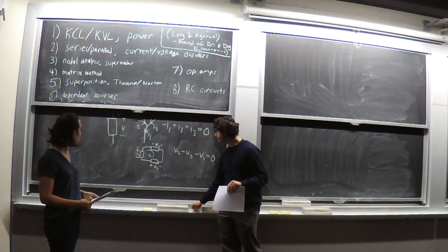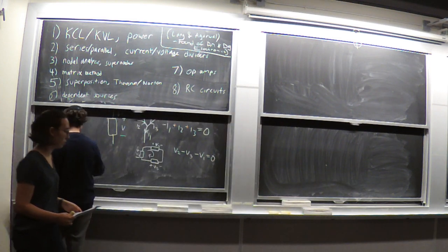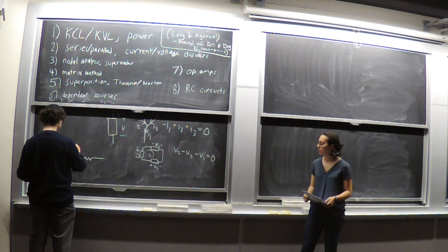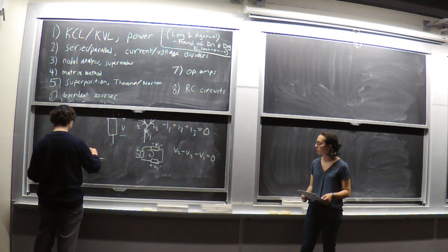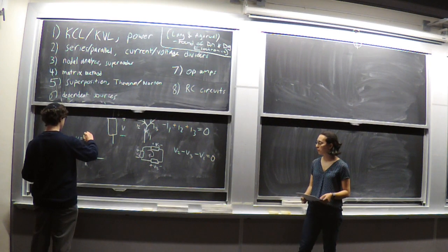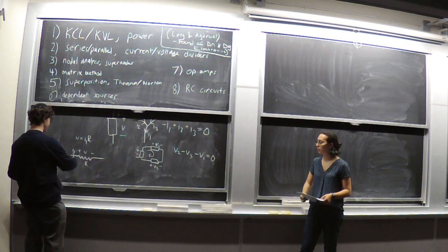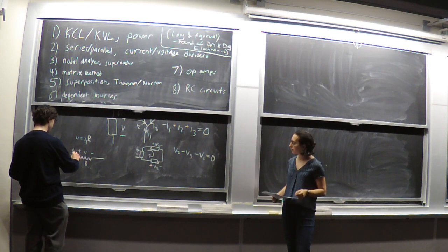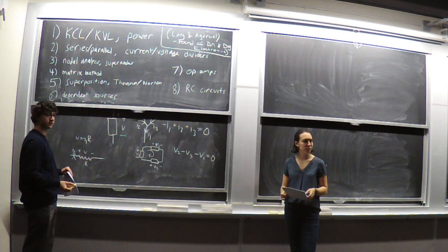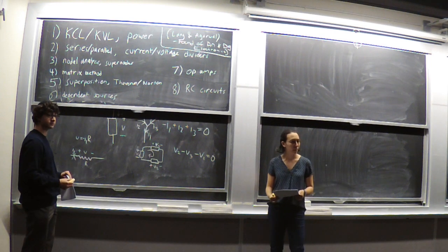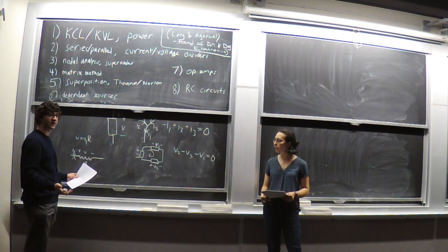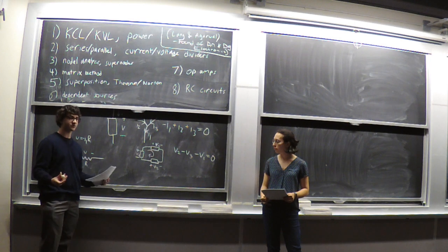And so, if we have a resistor, and we've defined some current going this way, and the plus and minus V, and this is resistor R, then we will have that V equals I1 times R. If this I1 were pointing in the other direction, then we would have a negative sign here, even though there's no way for a resistor to be supplying voltage. The idea behind that is that V and I1 could be negative.